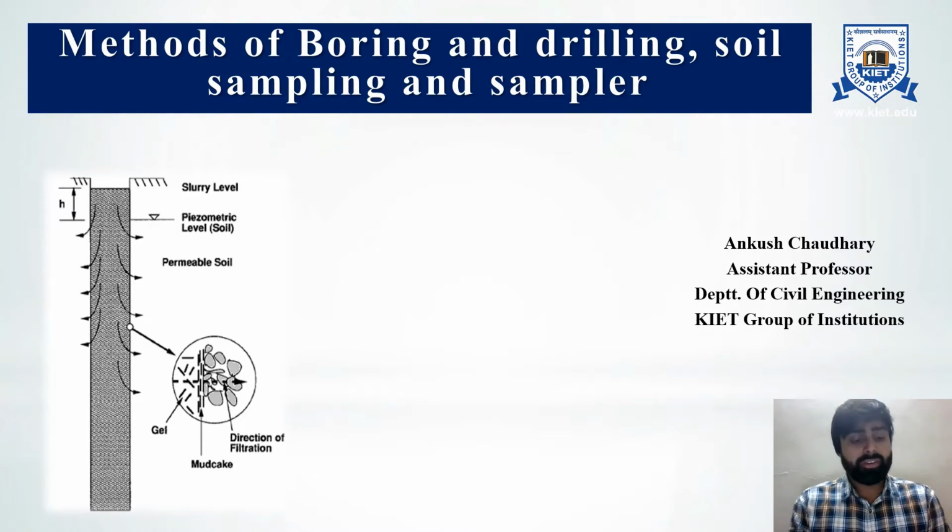When the depth of the exploration is large, borings are used for exploration. A vertical borehole is drilled in the ground to get information about the soil strata. Samples are taken from the borehole and tested in a laboratory. The borehole may be used for conducting in situ tests and for locating the water table. An extensometer or pressure meter may also be installed in the borehole for measuring deformation in the substrata.